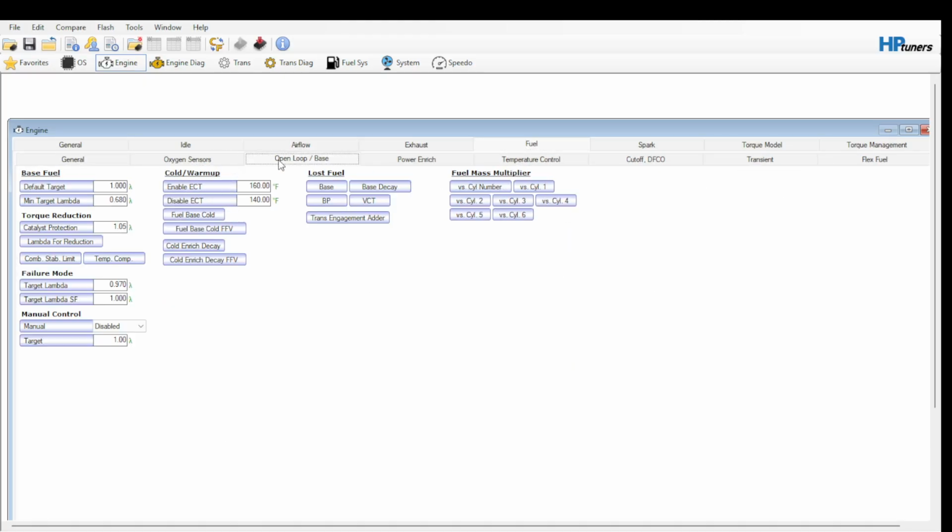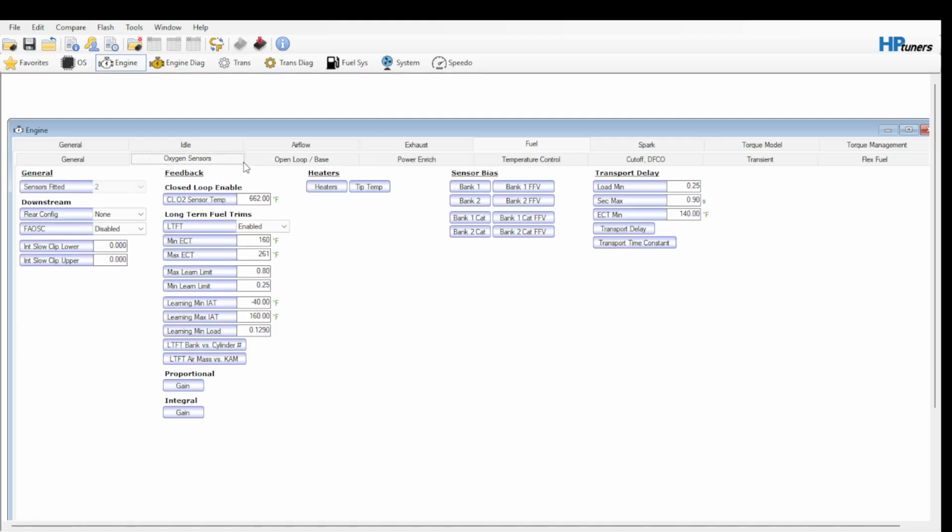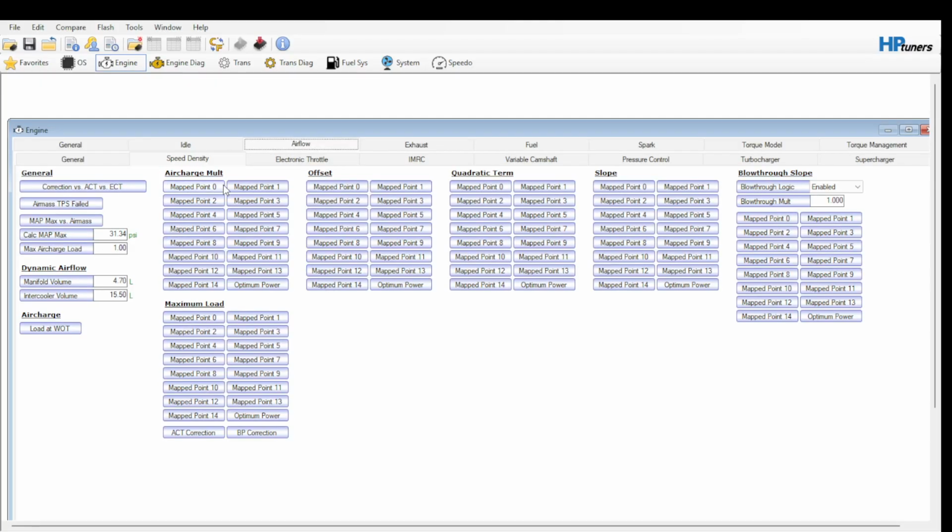But the problem is if you go into open loop or closed loop in your sensors here, after any of these points, these temperatures, the engine doesn't care what these values mean anymore. These values are totally ignored. Your sensors in the exhaust, that is your O2 wideband sensors that you can see in your logs, they're like the 4 bars, I believe, in the stock setup. They're going to be the source of truth, right? They're going to be what your truck identifies as God's word, if you will. Nothing else comes higher.